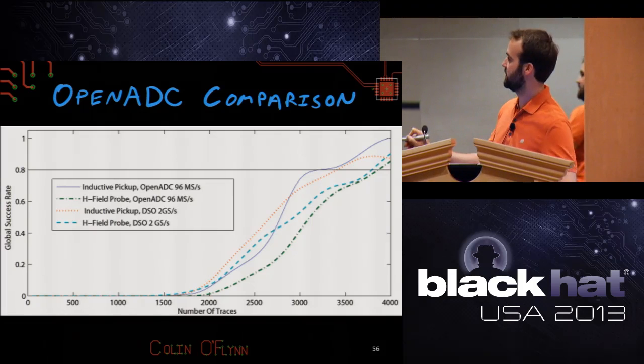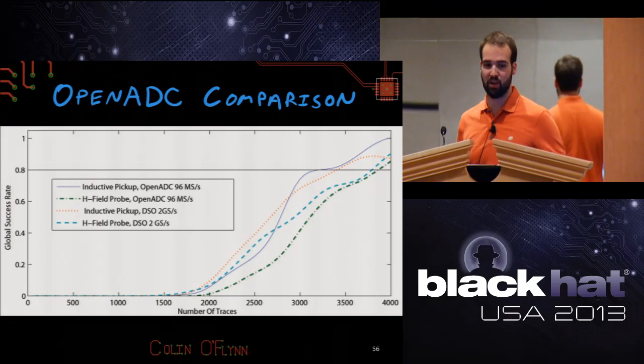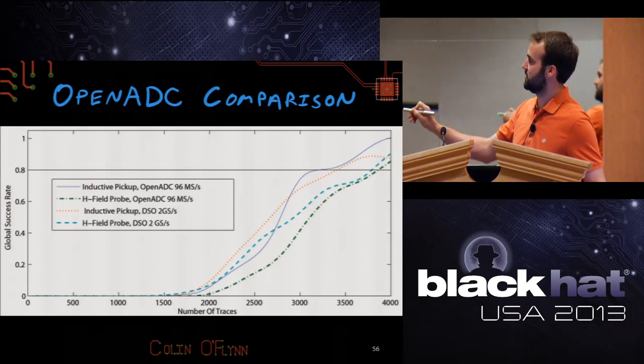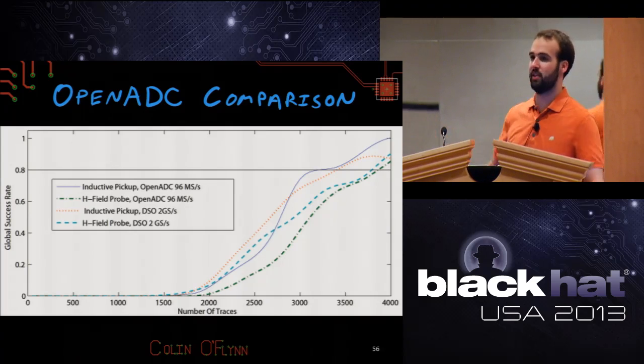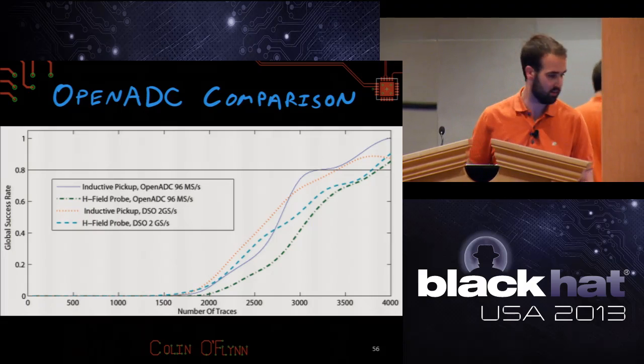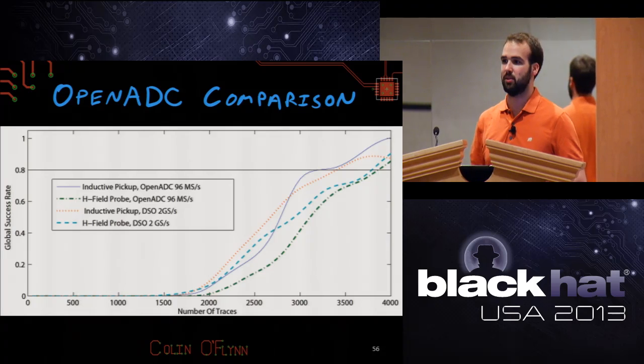It takes more traces, so here it's taking 3,000 traces, and there's a different metric plotted here. This is the success rate. So I'm saying if I measure the power 3,000 times, 80% of the time I can recover the exact correct key in this hardware implementation, even though it's doing everything at once. So it does in the end work out.